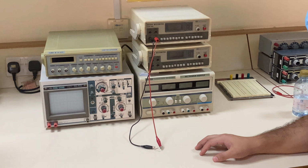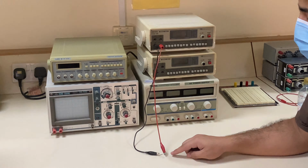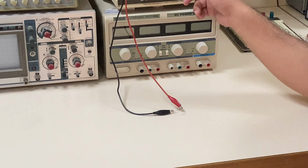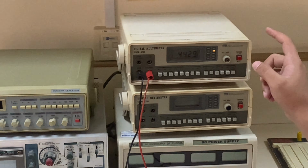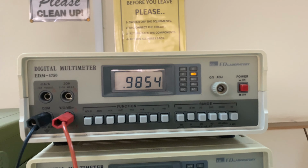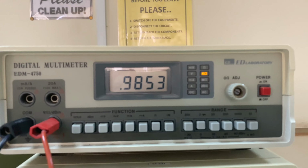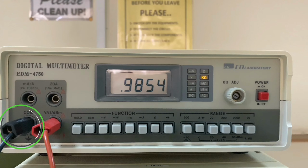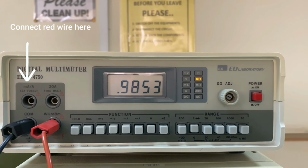Welcome to the lab circuit. We will start now the first experiment, in which we measure the value of the resistor using the multimeter, and how to connect the multimeter to measure the resistance. First of all, you need to power on, then you connect, as you see here. If you want to measure the volt or the resistance, you need to connect the positive wire to this plug, and always connect the negative wire to the common plug. And if you want to measure the current, you need to connect the positive in this plug.